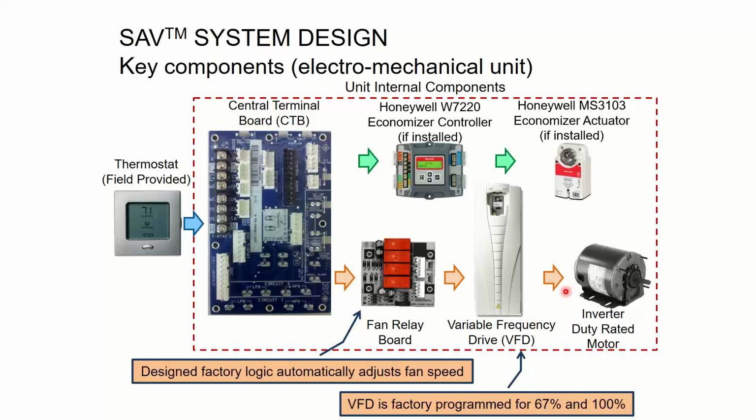Now you're also going to need an economizer controller that can handle that, because not every economizer controller has the ability to have 2 damper positions. Some of them, like this Honeywell Jade controller I'm showing here, can do it. The Belimo Zip controller can do it. I'm sure there's others as well. I'm going to need one that can have 2 minimum damper positions.